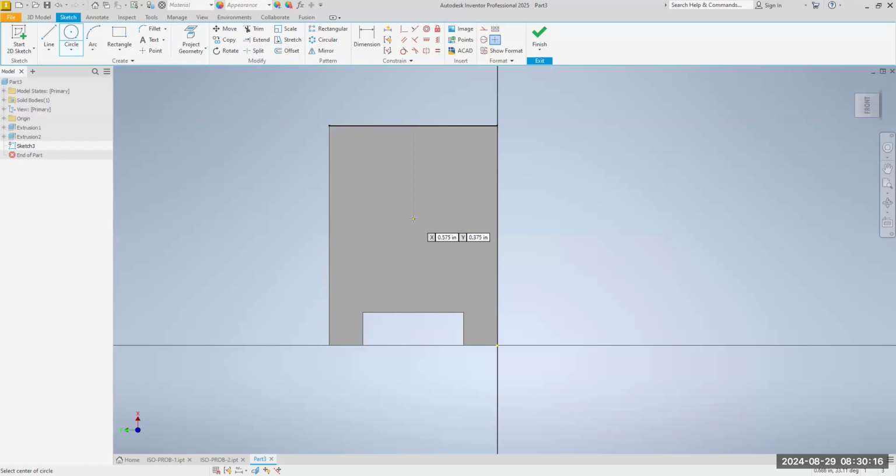And if you don't want to lose the line, the line is telling you that's a ghost image of an inferred line. I call it a ghost image of a line because it's not a real line. That's telling me that the circle is centered. Click, and I'm going to drag out a circle of arbitrary diameter, left click, do a right click, okay.